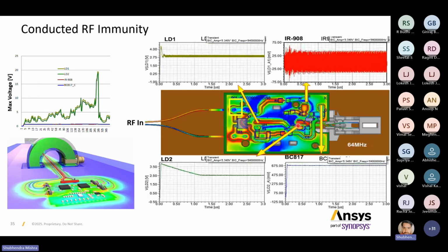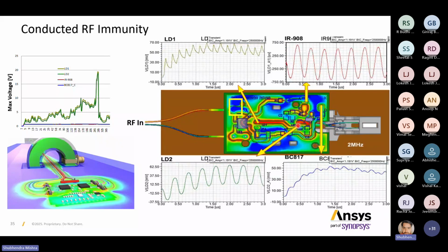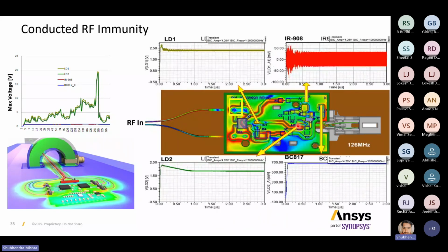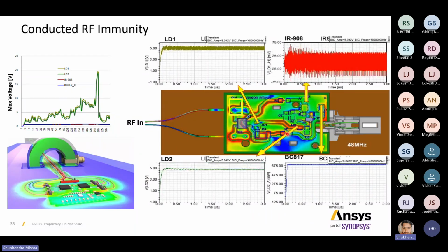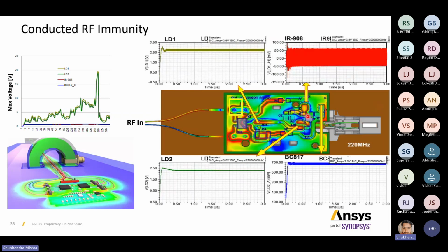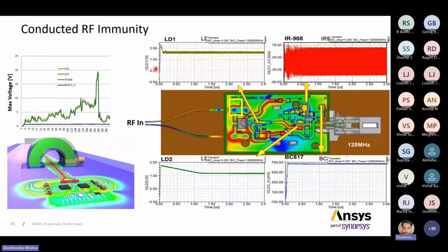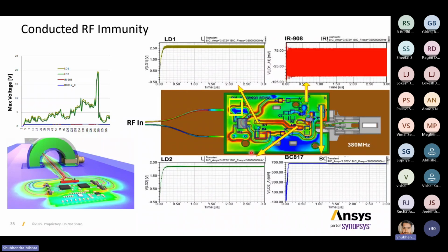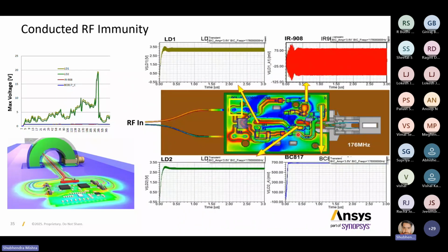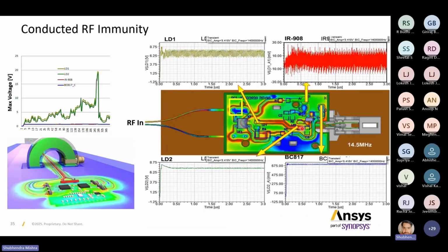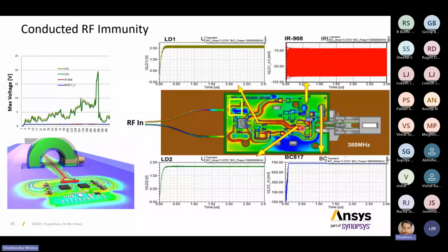So this is basically a conducted RF immunity test. In this, we analyzed that there are 4 critical points we have to work on. Now I want to analyze at each time how voltage is varying. For that, we will incident a plane wave on these 4 critical points, and after that, we will analyze how much voltage is varying with respect to time for each of the 4 points. With this, we can analyze the cause of our interference, and at which particular time we are facing the problems.